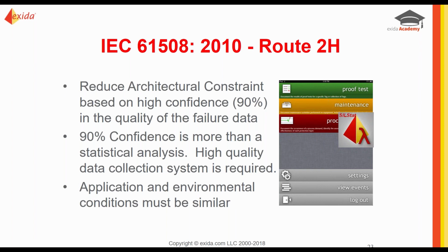Application meaning, if all of the SIFs you're looking at are close on trip application and you're starting a open on trip application, that could behave very differently. What if different environments? What if you are actually putting your SIF topside or subsea? You can't take that information from a cabinet mounted or an inside climate controlled application environment and think that this is an apples to apples comparison. So if you are collecting data to try and build a high confident data collection system and high confident data, you need to do apples to apples.